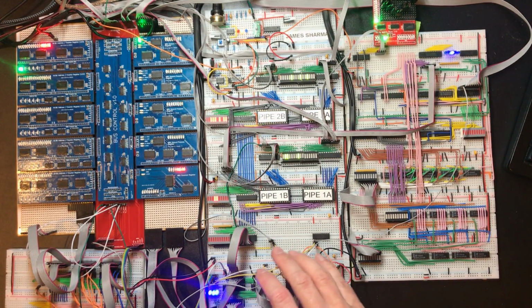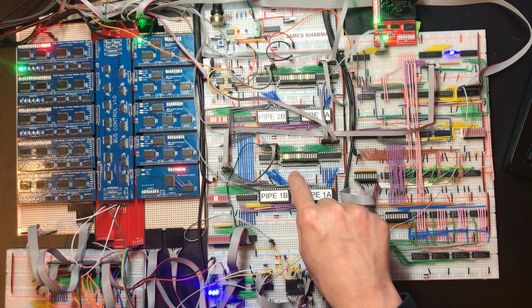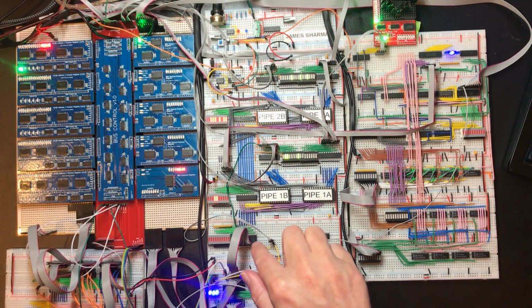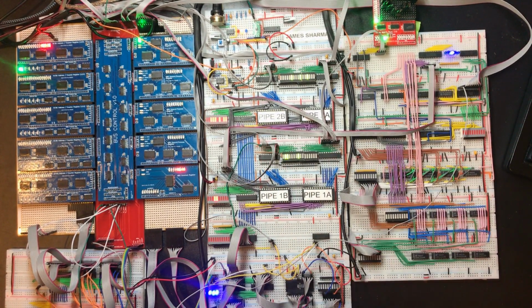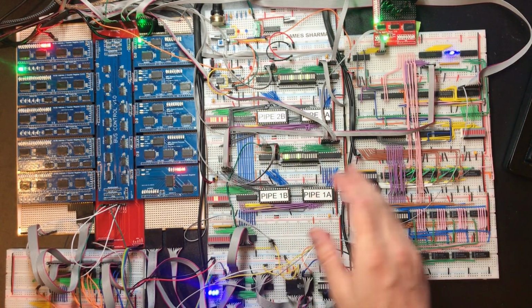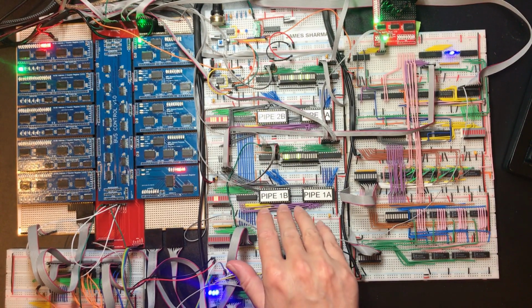So one way we could solve this problem is we could have an extra control line coming out of pipeline stage 1, which we then OR into that increment control. Unfortunately, we've got no control lines spare in pipeline stage 1. Now, obviously we could expand it, stick an extra ROM in there, but I'd really like to avoid doing that for a single control line.